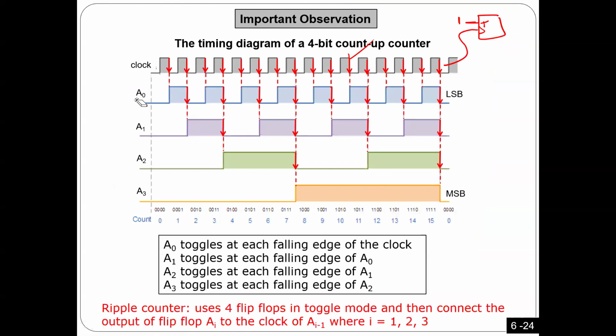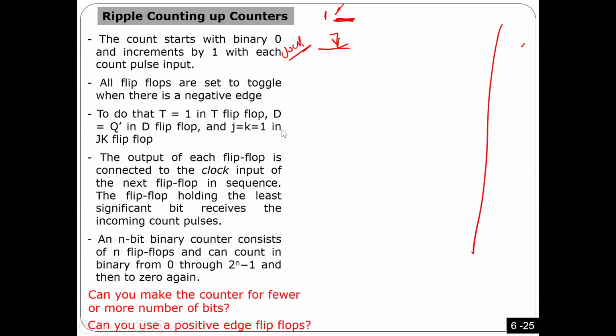Okay, so now I know how I can get this signal. Now for A1, how can I get this signal from A1? Again, you can find I have a flip-flop toggling all the time, but the clock is actually coming from here, so it has to toggle at this. So this is how the signal is. Every time there is a falling edge here, this one has to toggle in order to get this signal here. Okay, that's exactly what I did.